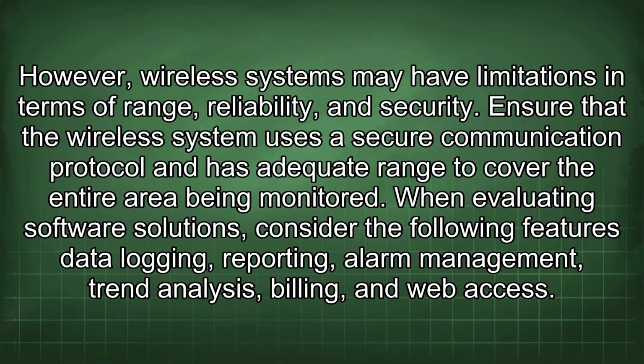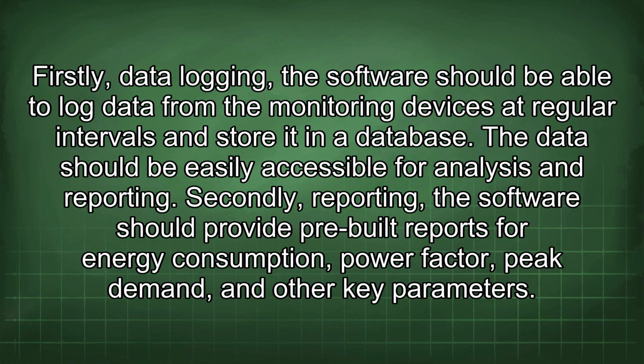When evaluating software solutions, consider the following features: data logging, reporting, alarm management, trend analysis, billing, and web access. Firstly, data logging. The software should be able to log data from the monitoring devices at regular intervals and store it in a database. The data should be easily accessible for analysis and reporting.